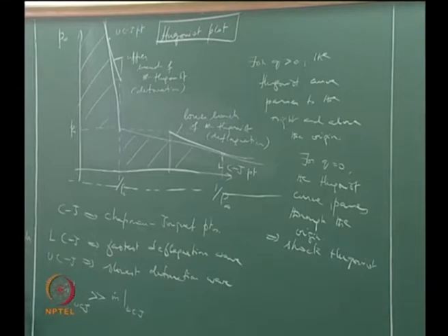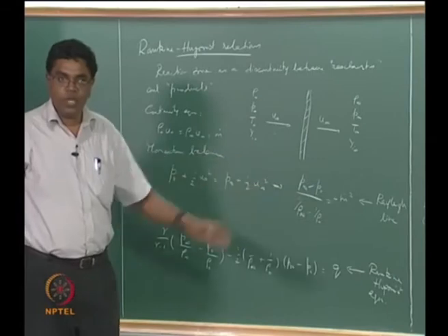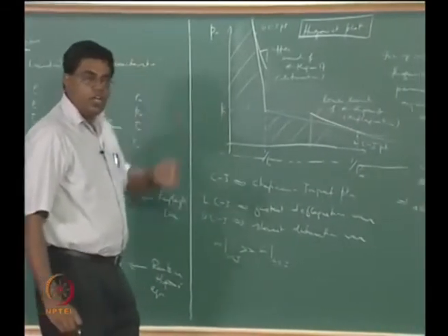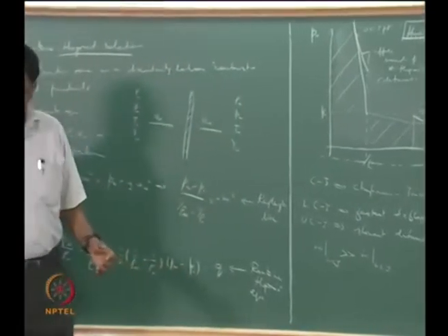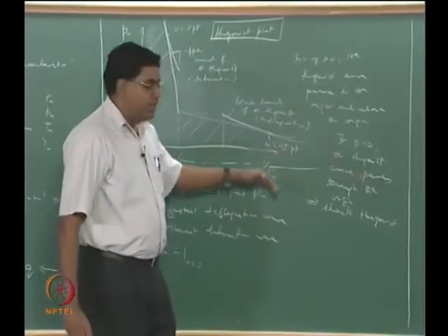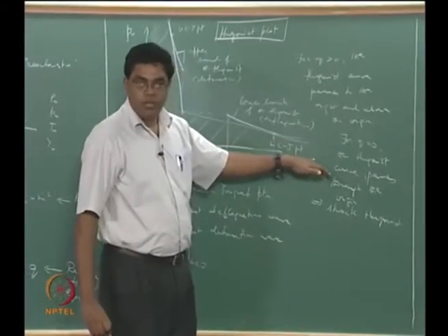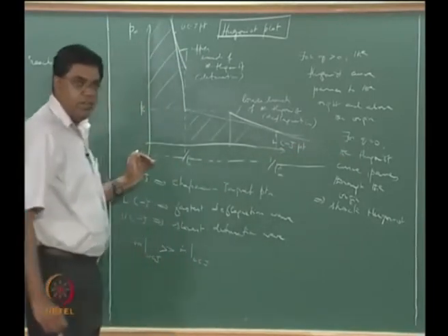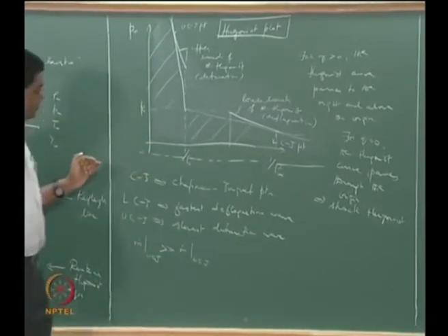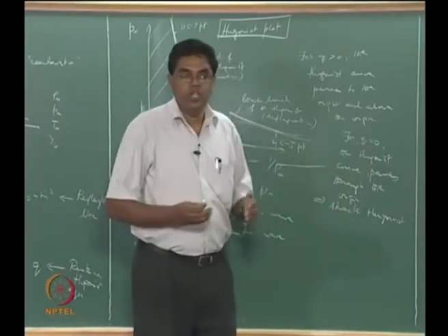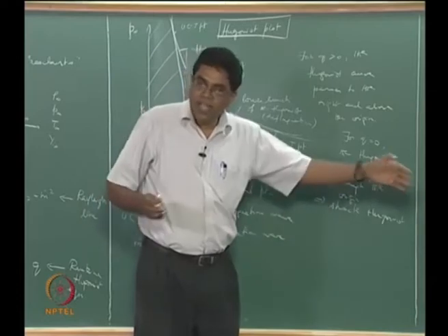So what you can actually do is go ahead and find out the horizontal asymptote for this rectangular hyperbola, and you should find that that's negative, and since you can't admit negative pressures in reality, you don't worry about where exactly it asymptotes, and you have to stop thinking about it where it hits the abscissa. That's corresponding to your P infinity equal to 0, and then there is a corresponding 1 over rho infinity, that's the maximum value to which the products can expand.